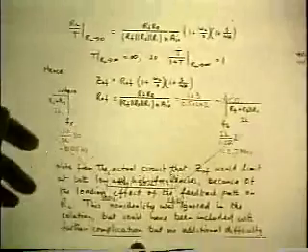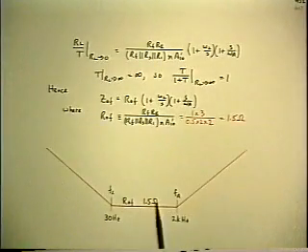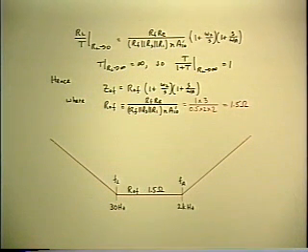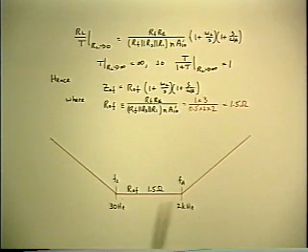Okay, now another comment about the output impedance. It's very low, but only over a pretty narrow range, which means the damping factor for the loudspeaker, which is part of the design criteria, is not so good when you start getting outside that range. Now, the design of a speaker is sort of a special case of a load. It's a pretty complicated electromechanical system on its own.